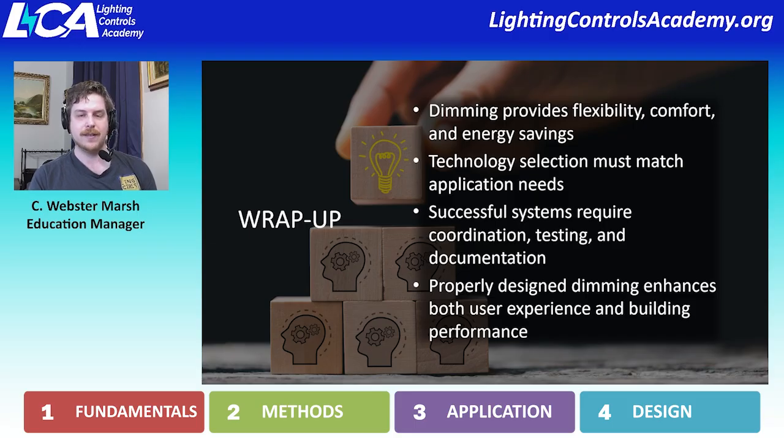It provides a lot of flexibility, comfort, and energy savings, but we want to make sure that we're matching that application to the needs of the application. So which dimming is going to be most appropriate really is determined by the occupants using the space. So we want to coordinate and make sure that the dimming is there to enhance the user experience and the building's performance. And we do that by doing proper coordination, testing, and documentation.